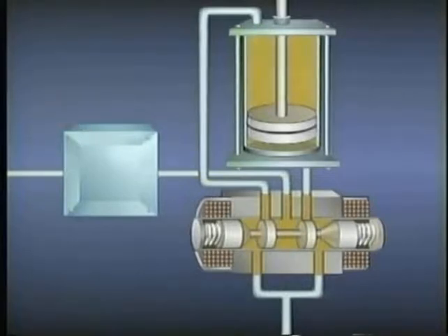The flow control valve is placed in the supply line before the directional control valve so that the flow of fluid supplied to either side of the actuator can be controlled. With this arrangement, fluid flows through the supply line to the flow control valve, which then measures or meters the proper volume of fluid into the directional control valve.